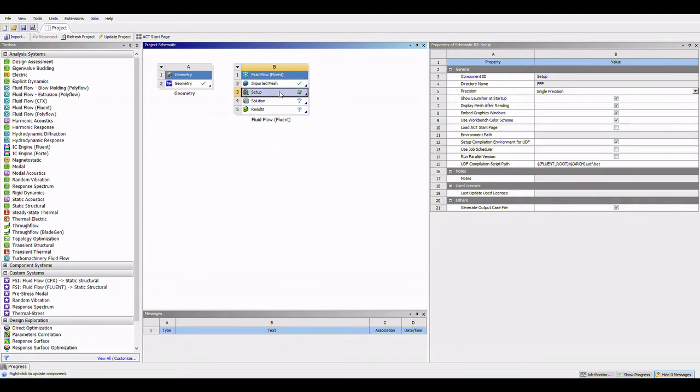After it's open, we're going to go to the ANSYS Fluent setup. We're going to start Fluent in double precision mode and parallel mode with the amount of processors available in your PC. I'm going to click OK.